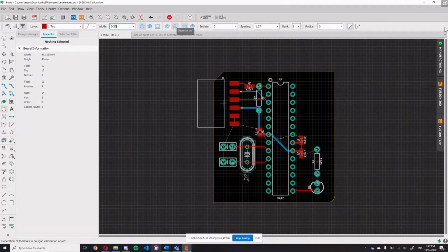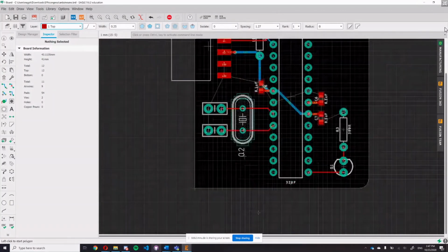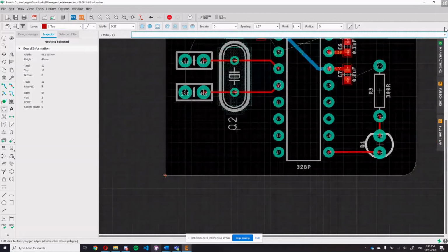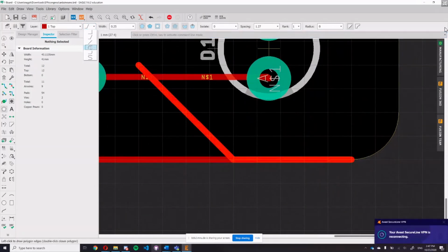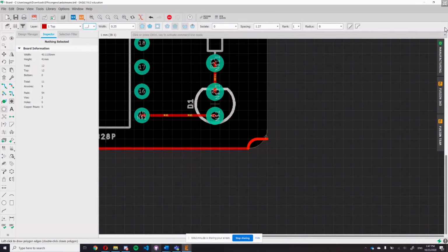We also have some other settings here. Thermals on. Yeah, this is fine. And we have it set to the top layer. So top layer, 0.25, hatches on. So we start copying the shape of the outline. So we start here, we go here, and now we want to select this curved thing again.